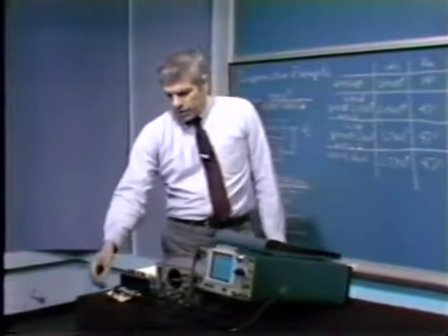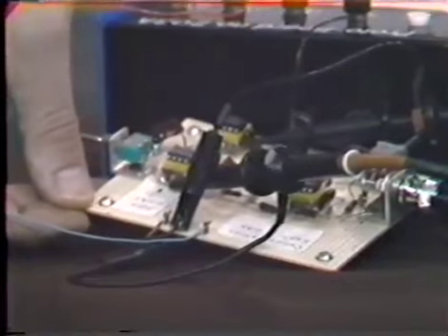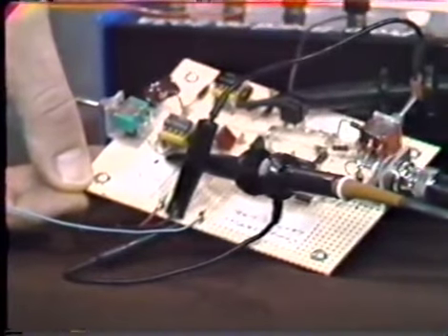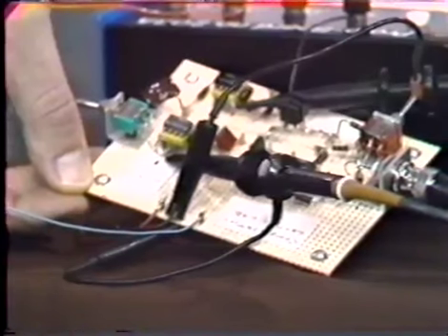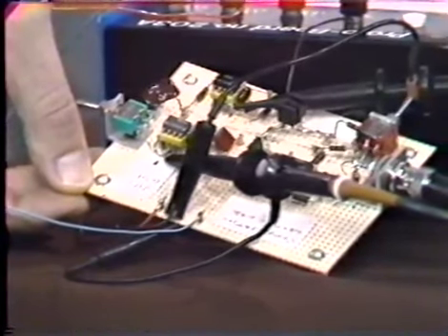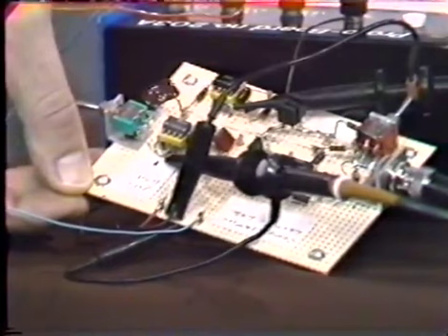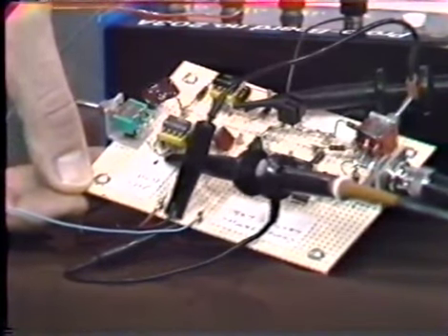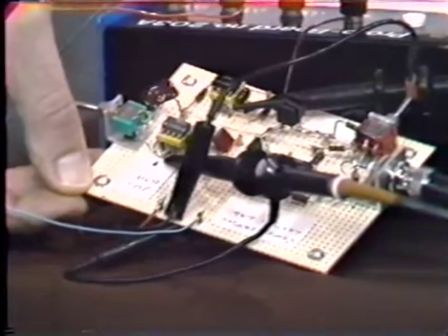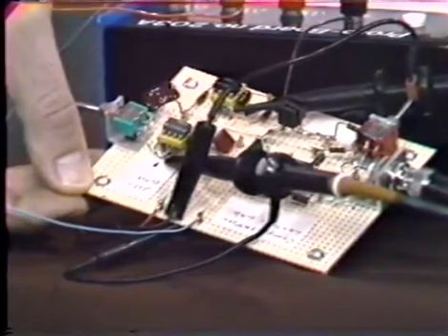And what we have here is a little board that's effectively our pseudo amplifier. We actually make it up out of several operational amplifiers, as you can see. We have networks that fairly precisely locate the poles associated with our pseudo amplifier, the poles at omega equals 1 radian per second, and at omega equals 10 to the fourth radians per second, and at omega equals 10 to the fifth radians per second.